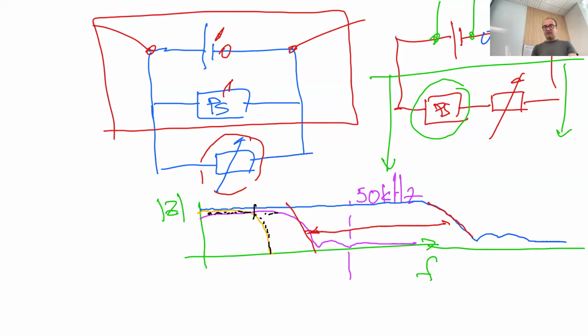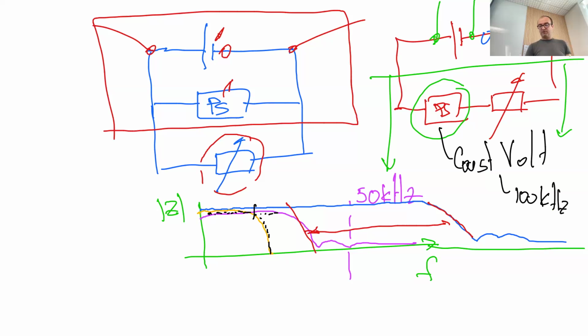That is why we always operate the power supply in constant voltage mode, because if you look at the data sheet, the constant voltage mode has bandwidth most probably up to 100 kilohertz. And on the exact same power supply, the constant current bandwidth can drop down even below 300 hertz.